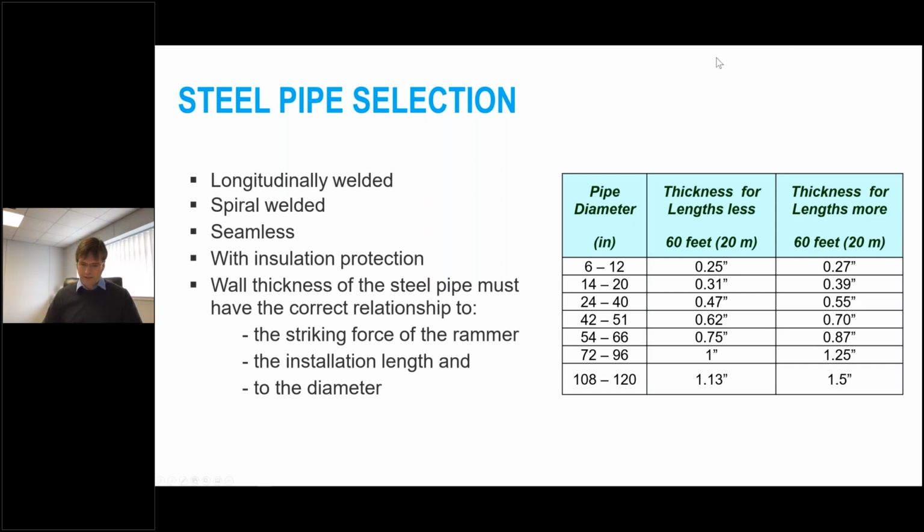And just to give you an example on how to read this chart, take, for example, a 500mm pipe, or 20-inch pipe, that we would want to install over a 25-meter distance. We would always recommend a minimum of 10mm wall thickness. So the inner diameter of your product pipe cannot be more than 480mm maximum.